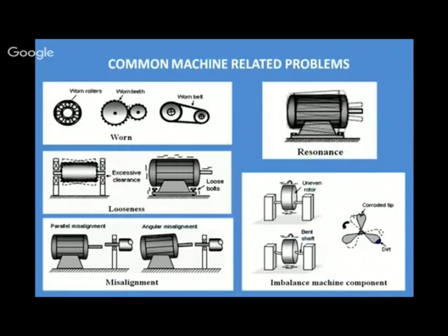Here we have misalignment fault also. So these types of faults are basically produced at the time of installation, and there are some faults which occur at the time of operation of the machines, like imbalance because of some dirt or corrosion of the moving part. So the reason of fault may be any of these types of abnormal operating conditions.